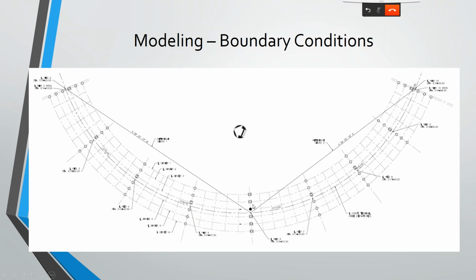At this point, you can see that these ones have a longitudinal restraint on either side. This will be the fixed pier, so we've not let that move longitudinally. This is using a slotted hole and anchors in order to achieve that. So transversely, we're allowing movement, but longitudinally, we are not. And you essentially just don't want to lock anything up, or if you do lock things up, you need to take that in force. So you either take it in movement or you take it in force.